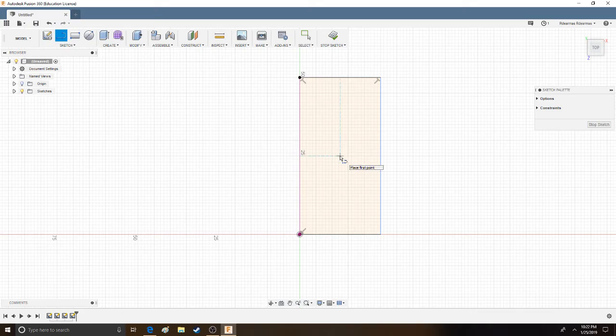So it does not show here. It only shows on sketches. So completed sketches don't count. This does have the directions, though, which is pretty cool. The directional lines on it. So we're going to select that middle point and drag that across to the other center on the other side. There we go. And of course, once you've completed a center to center, it shows that this line was created at the center by that little holographic triangle in the corner.